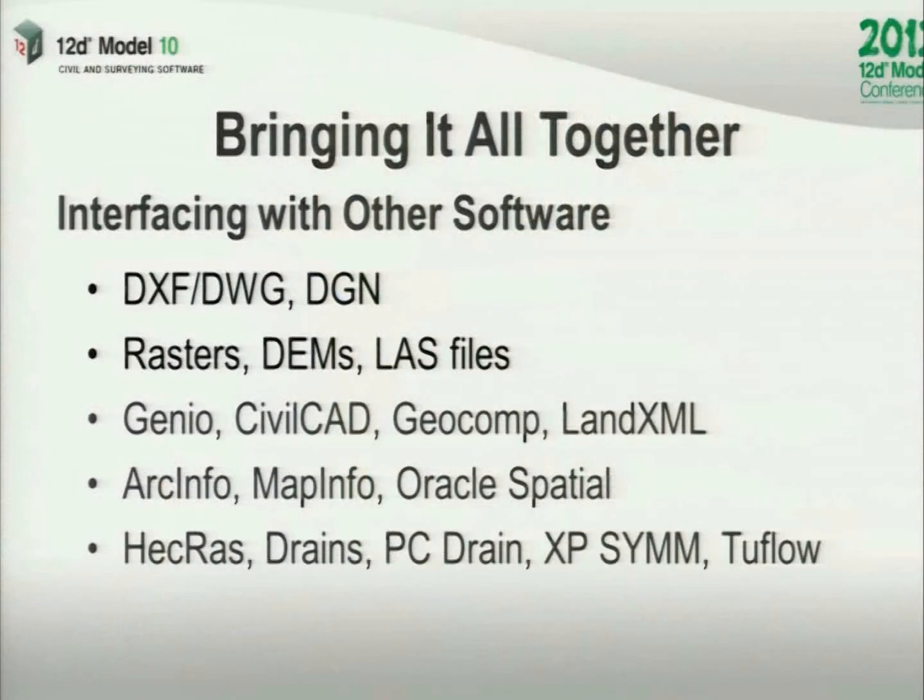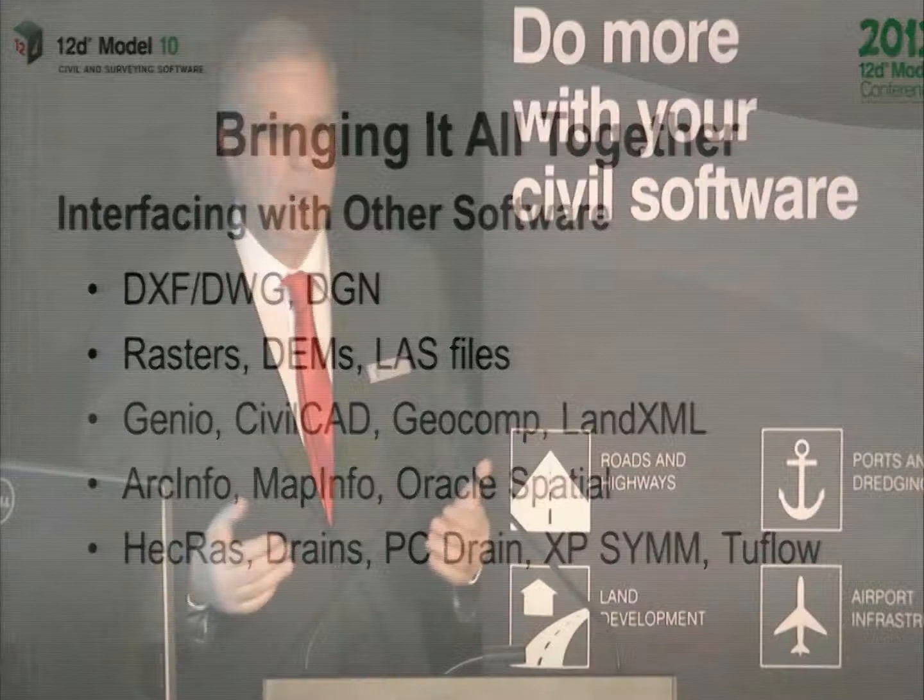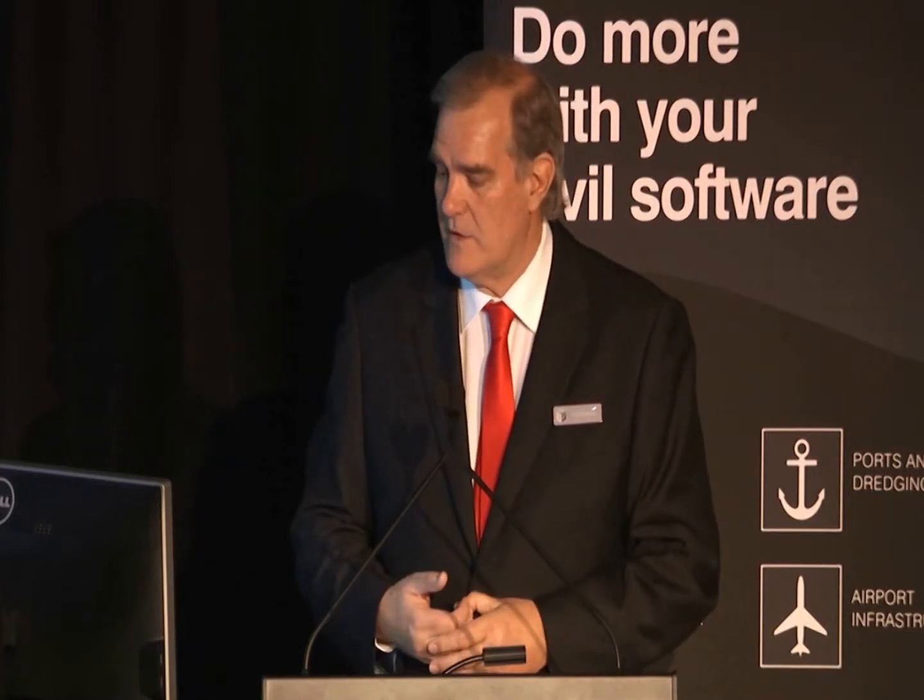Interfacing with other software. We believe no man's an island. Anyone who says they have all the software solutions is lying to you. We've always believed you should be able to communicate with as many different packages as possible, and we've tried to do that, although many of them take a lot of our time. DXF, DWG: every time they change the proprietary format, we have to spend a lot of man hours trying to get it to work. DGN, the same thing with their new format. It's slower for us to do because there are not many people with it. But we try our hardest so you can get your data backwards and forwards.